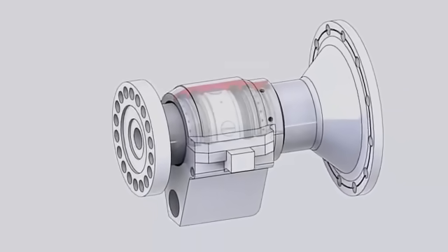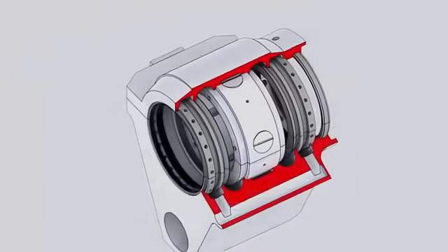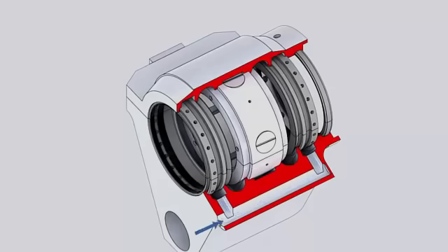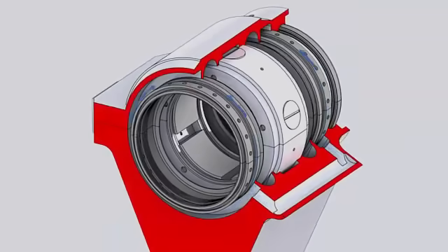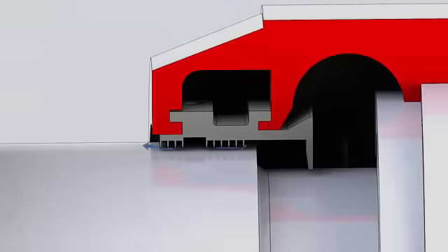Labyrinth seals are installed in housing where oil control is required. Their teeth run against rotor smooth surfaces. The sealing air flows from the cooling and sealing system through the axial tube machined at the left side of the housing and is admitted to the labyrinth seals through 2 ports to annular spaces surrounding the seals. Between the two rows of seal teeth, similar to other bearings, sealing air is admitted through multiple radial holes to stop oil leakage. Some of this air returns with the lube oil, and some escapes out of the housing.